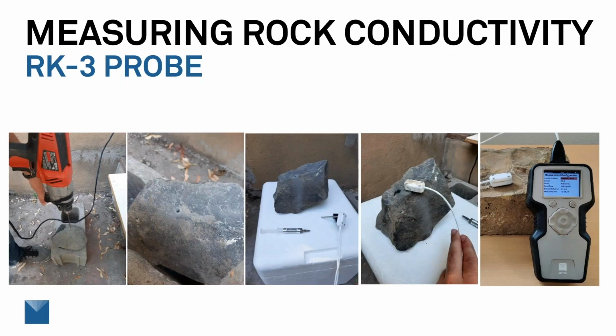Now let's talk a little bit about how we get the thermal conductivity measurements for the calculation we want to do. As I said earlier, some porous rocks have water content dependent thermal conductivity. And if you're dealing with rocks like those, you will need to determine that dependence. The rock we have here has very little porosity, so a single value for its thermal conductivity will suffice.